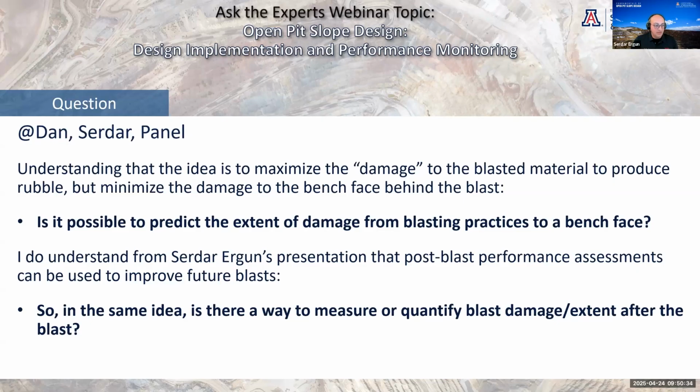On the other hand, we also get high resolution photogrammetry or LiDAR scans to generate pre and post blast point clouds and software to understand how the bench face behaved before and after the blast. So this will give you the damage extent by just making that comparison.